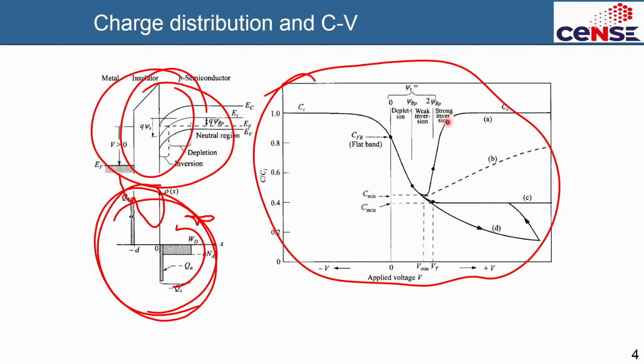and so you can come back to the original. You will basically move in and out of here. So exactly the oxide capacitance is the capacitance that you will measure, which is this oxide capacitance, and that's what happens at the low frequency sweep. So I told you this point, the minimum point where the capacitance becomes minimum or the depletion width becomes maximum, is the onset of strong inversion, where a strong electron gas density has formed.